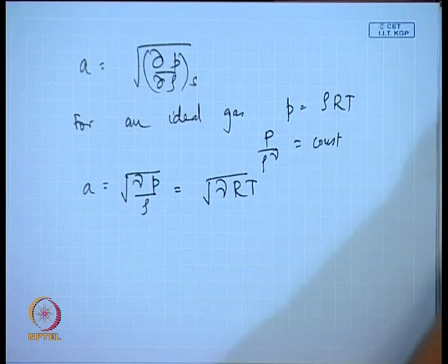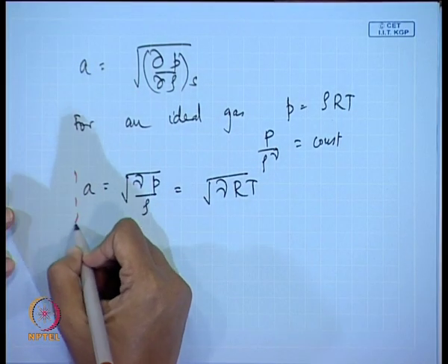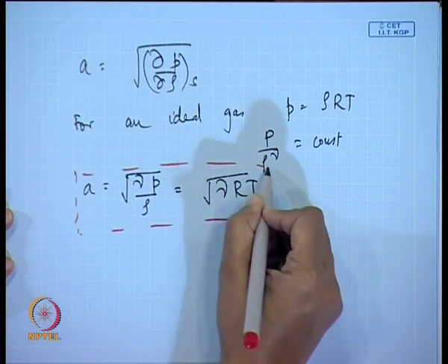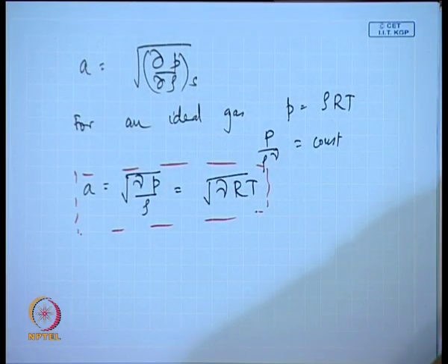So, by this process, we first found out how to define compressible flows. We found that Mach number is important. Now, in order to calculate Mach number, we need the velocity of sound. If we can relate velocity of sound under those conditions with measurable parameters, it is going to be very convenient. So, the next thing we did was express A in terms of the absolute temperature or in terms of pressure and so on. We obtained that A is equal to root gamma R T.